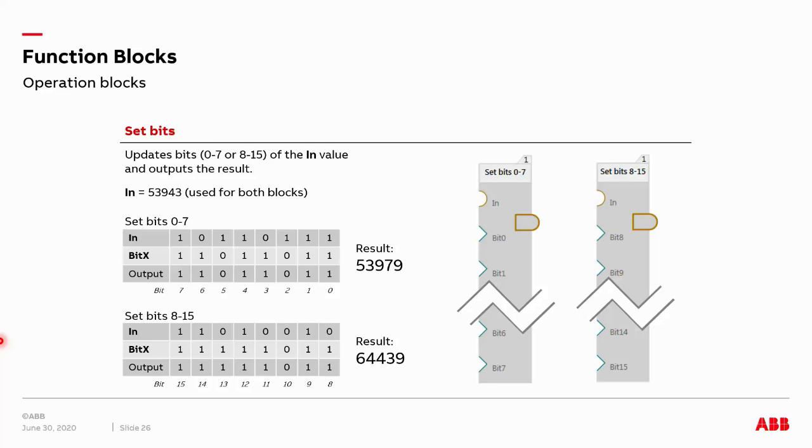That's the data type. Anytime I start using set bits and get bits, I'm really just using it for the binary numbers that exist. It just so happens to be a lot easier to show the decimal number when showing some trainings, but I really only care about the specific bits once I start looking at these types of function blocks.